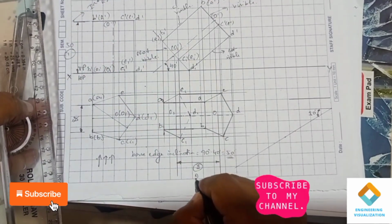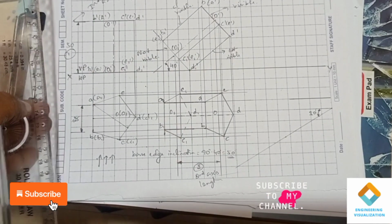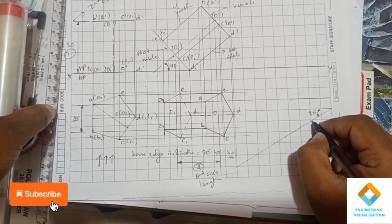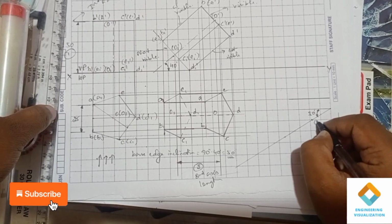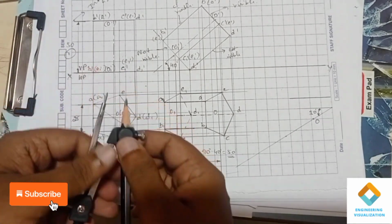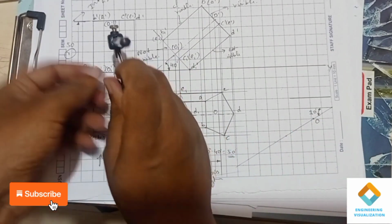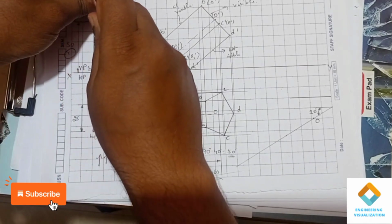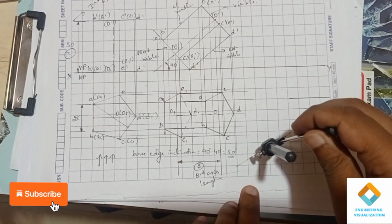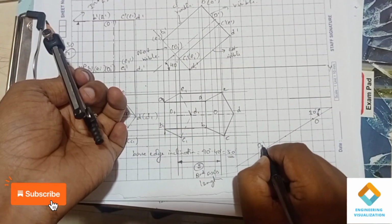Okay, so this is your second length we should consider. Second axis length: the first axis length given in the problem is 50. First take a reference point, that is your O. Measure the length of 50 mm from the compass and cut an arc. Here the axis length is 50 mm, so measure using the compass and cut the arc. To avoid confusion, we will call this O2.